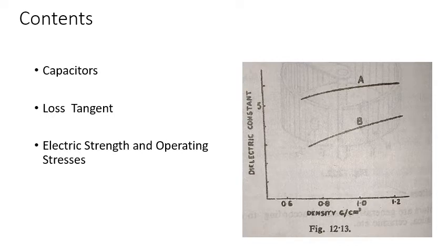In addition, it is necessary for the paper to be of uniform known thickness and for its tensile strength to be adequate for winding under diverse conditions of tension and width, which may range from 10 mm to 500 mm. So what is the capacitor paper?